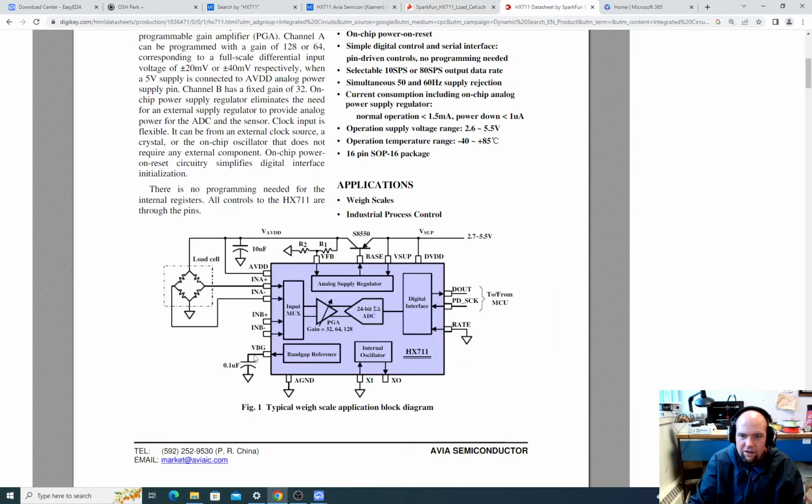So analog ground. Okay, so there's an analog ground pin which is grounded, and then the band gap reference capacitor. What this is doing is internally this chip is generating a reference voltage. Every analog to digital converter needs to have some known voltage to compare to. And in this case, they're producing a known voltage to compare to by using the silicon band gap. That's the potential energy difference between the two bands in a semiconductor material.